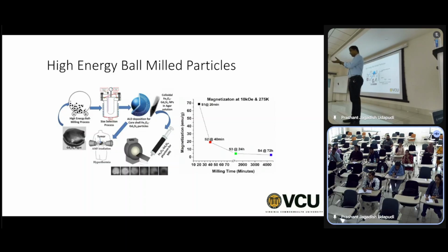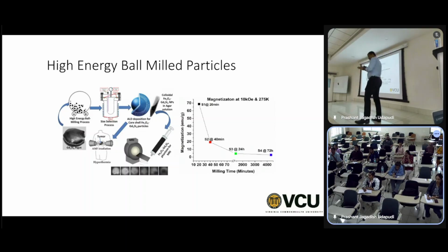It's called arc melting, right? You use an electric arc to melt. It's a common technique in laboratories. And you can also make smaller quantities. You melt both the materials and mix it with the arc or a stirrer, and it becomes a stoichiometric compound of 5,4, gadolinium 5, silicon 4.